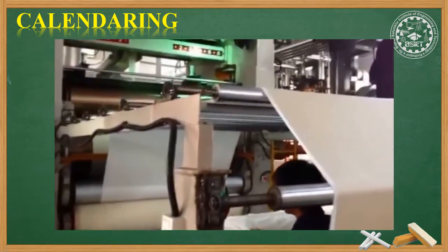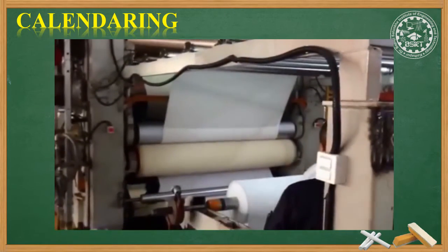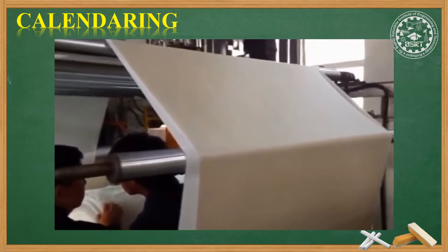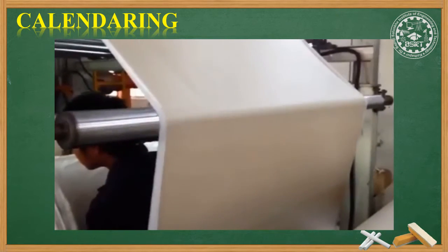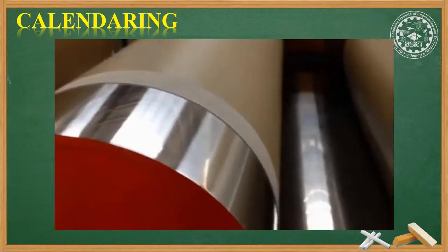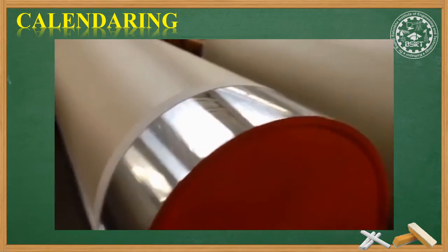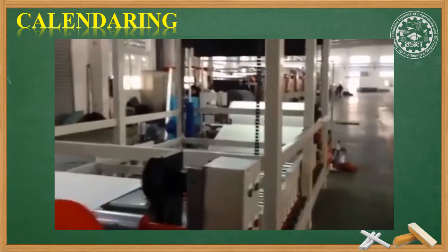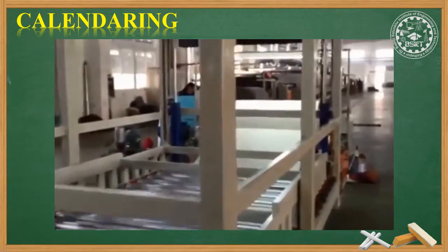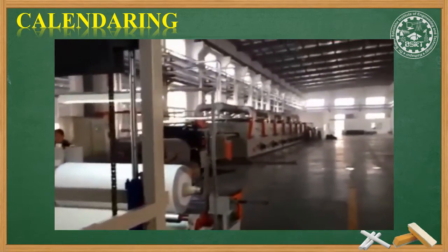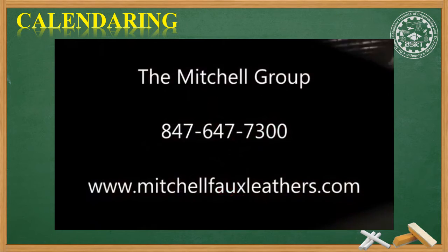So the third stage is then basically, as it got fused over there together, those were the two parts where they met. Here comes the clean sheet of PVC vinyl, and it gets cooled down through these cooling rollers. It gets wound up through the back side here, and then after this it'll go to this next station, which is the embossing station.